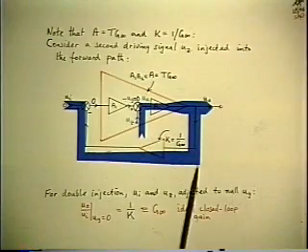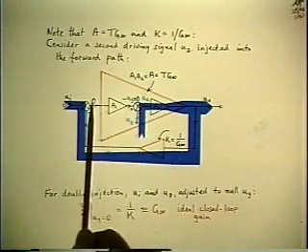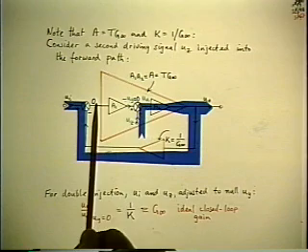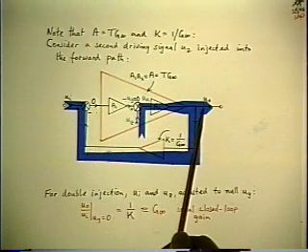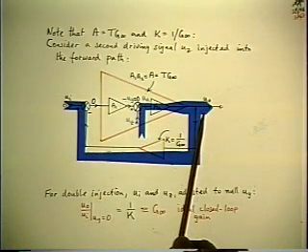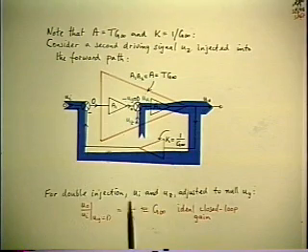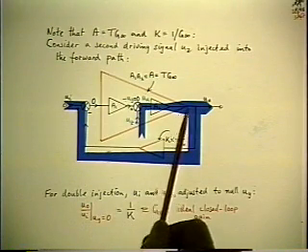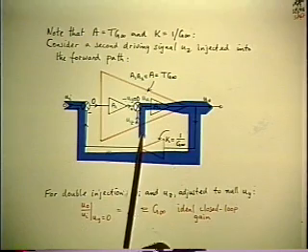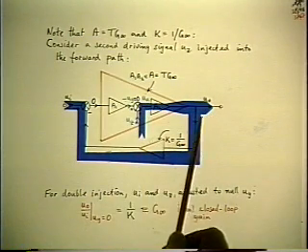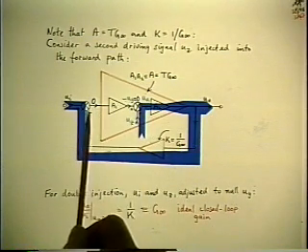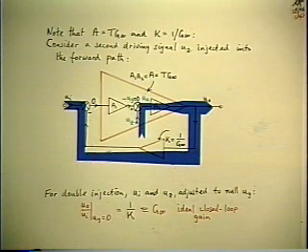Notice that this is equivalent to a simulation of infinite T, because you have a finite output from the forward path for 0 input, which is like an infinite A, therefore an infinite T. And the way you set it up is you fudged it by using the second input to drive the output to the proper level that takes over the position of the amplified error signal.